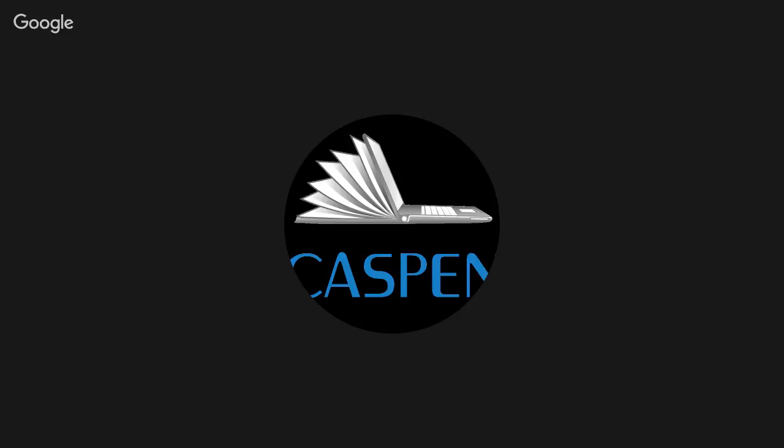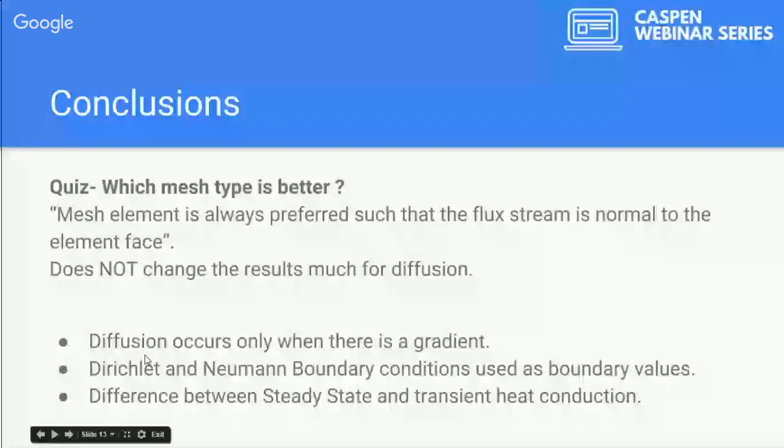and when to use what kind of a boundary condition. Dirichlet is used when you are giving absolute values, like we did for patch 2 and patch 3. And Neumann boundary condition was given at patch 1, Dirichlet was given at patch 2 and 3. And the difference between a steady state and the transient heat conduction, where the transient heat conduction happens at each time step of physical time and not the simulation time. And in the steady state, we'll only be matching the time for the simulation to occur.